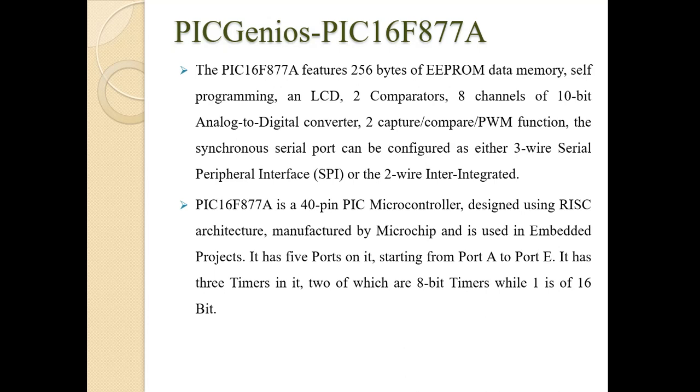PIC16F877A is a 40-pin PIC microcontroller designed using the RISC architecture, manufactured by Microchip and used in embedded projects. It has 5 ports on it, starting from port A to port E. It has 3 timers in it, 2 of which are 8-bit timers, while one is 16-bit.